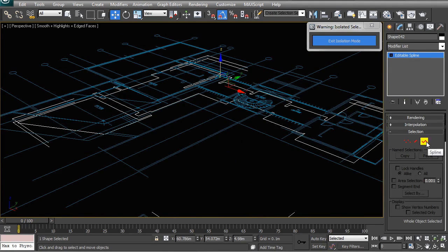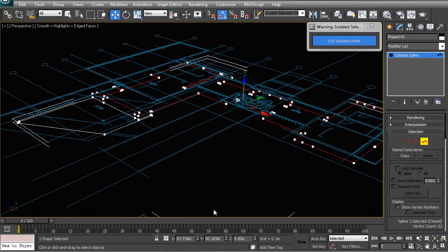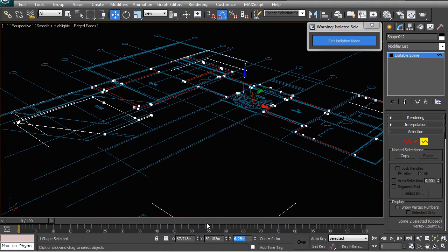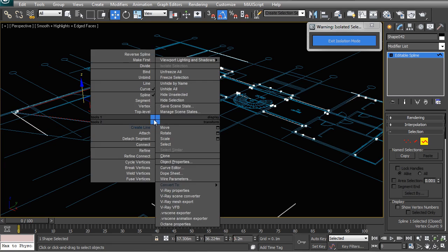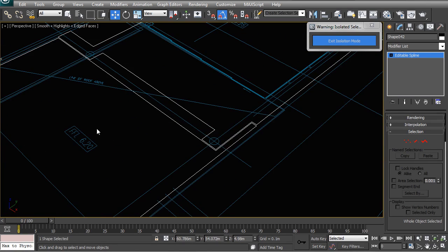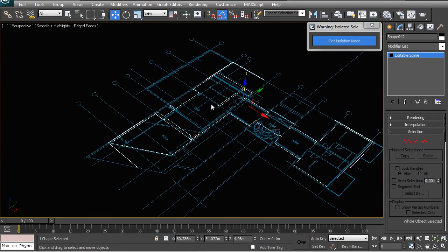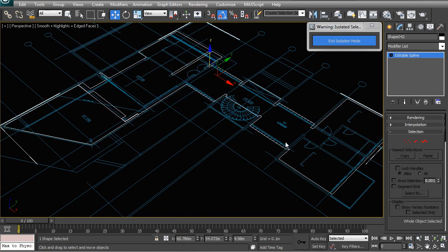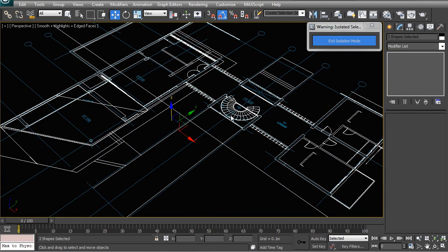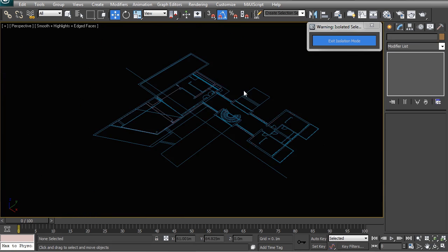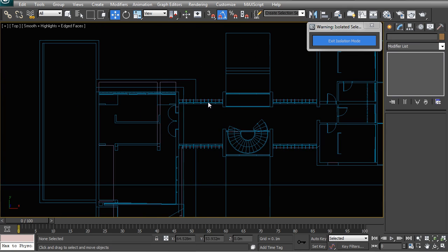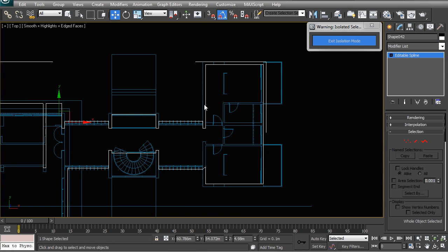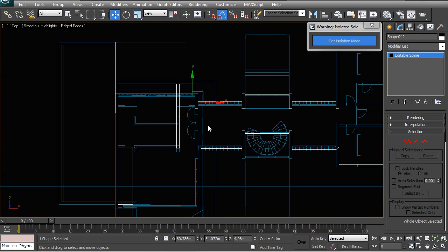And I'm now going to choose the spline, and I'm just going to manually move it up to the right height. So I'm going to type in 6.25 for this one. And this one is going to be 6.2. And those heights are mentioned for you over there and there. What you can do now is you can take this slab and isolate it further just to remove the grids layer, and you can start looking over it in detail and seeing where you can start tweaking it, modifying it, and working with that spline.